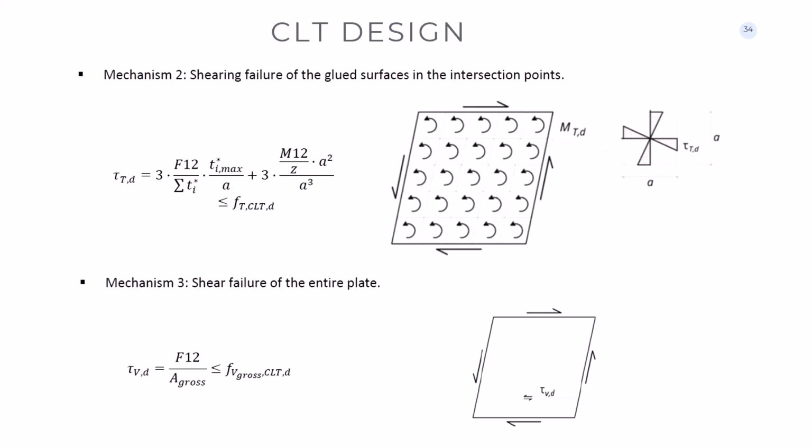So conceptually, it's very easy because you have a bunch of formulas, all based on results from a pure shell elastic analysis. So you take the F1,2, the F2,1, the M1,2, M2,1, and so on. You combine them together with this formula, and you get stresses that you can compare with a stress limit. So it's very easy conceptually. The problem is that there are a lot of equations and a lot of shells and a lot of nodes.